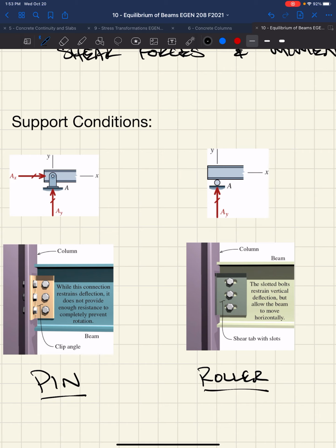With pre-stress, you put a bunch of steel in the concrete, but in order to get the capacity out of it, you end up squishing the concrete, because it's bad in tension and you never want it to go into tension. So they create these big, long beds, put tendons in them that they stress, pour the pad, and cut the tendons. The stress that was in the steel rods, which we had in tension, now transfers into the concrete wall panel and squishes it.